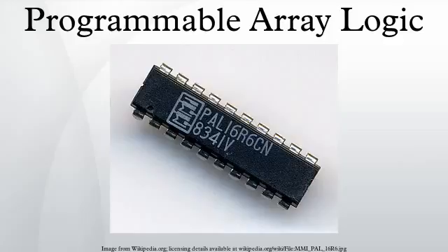Output logic: the early 20-pin PALs had 10 inputs and 8 outputs. The outputs were active low and could be registered or combinational. Members of the PAL family were available with various output structures called output logic macrocells, or OLMCs. Prior to the introduction of the V-series, the types of OLMCs available in each PAL were fixed at the time of manufacture.